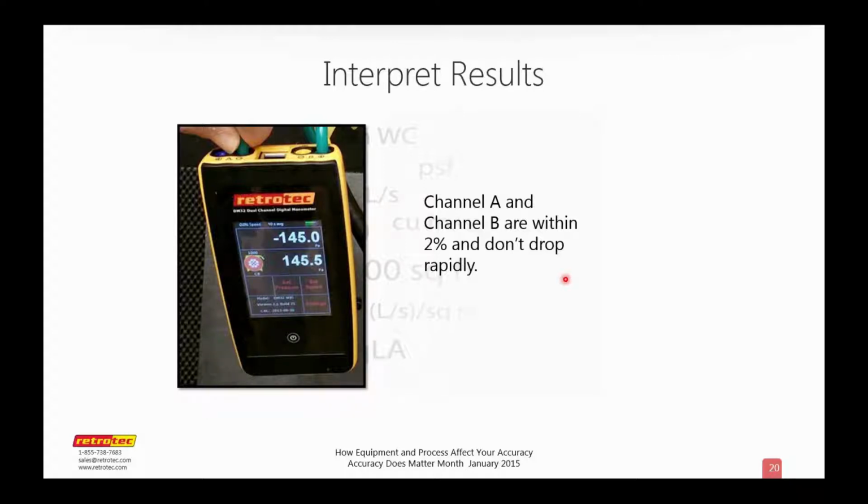So here we're going green to green, so try a yellow tube and go yellow to yellow, and then you're checking the tube and the gauge at the same time, and it could be either one that's at fault. If the yellow tube gives good results, then it's obviously something wrong with the green tube. Right, sort of deductive reasoning. Thank you for pointing that out.